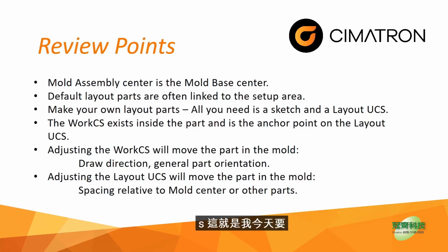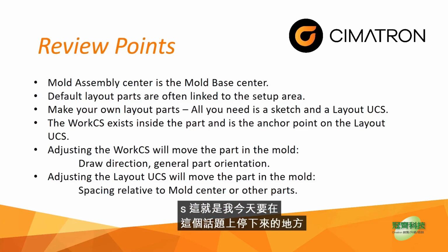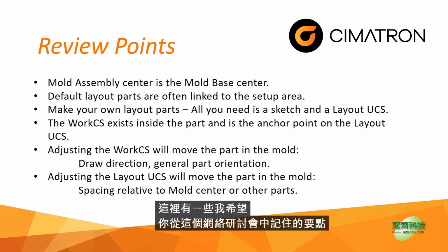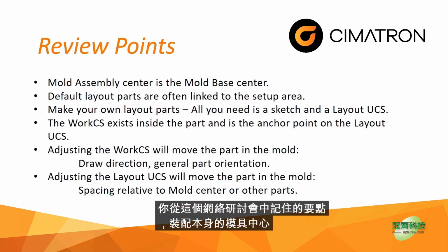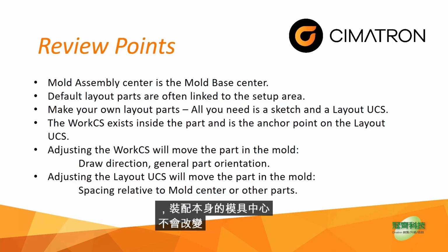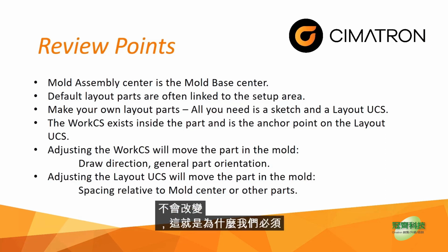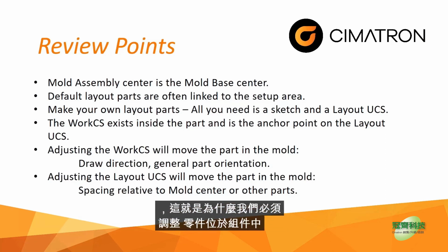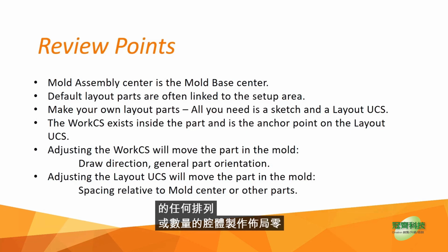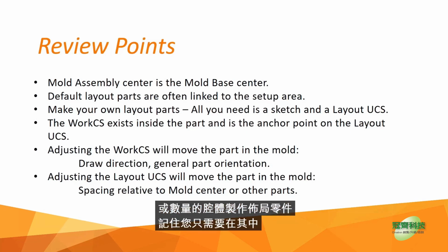And that's where I'm going to stop on the topic today. Here are a few of the high points I want you to remember from this webinar. 1, the mold center of the assembly itself does not change. And that's why we have to adjust where the parts sit in the assembly. Also, it's really easy to make a layout part for any arrangement or number of cavities that you're going to have. Remember, you only need to make 2 features in it, so really easy.